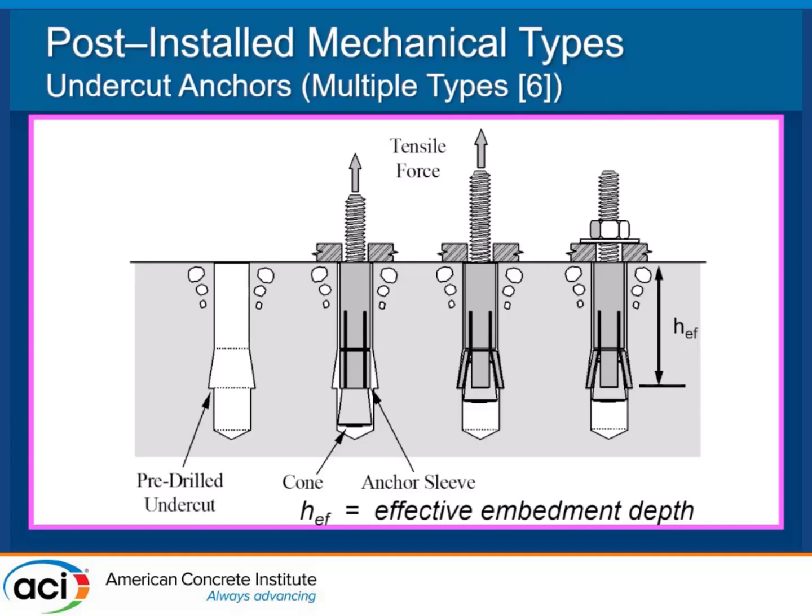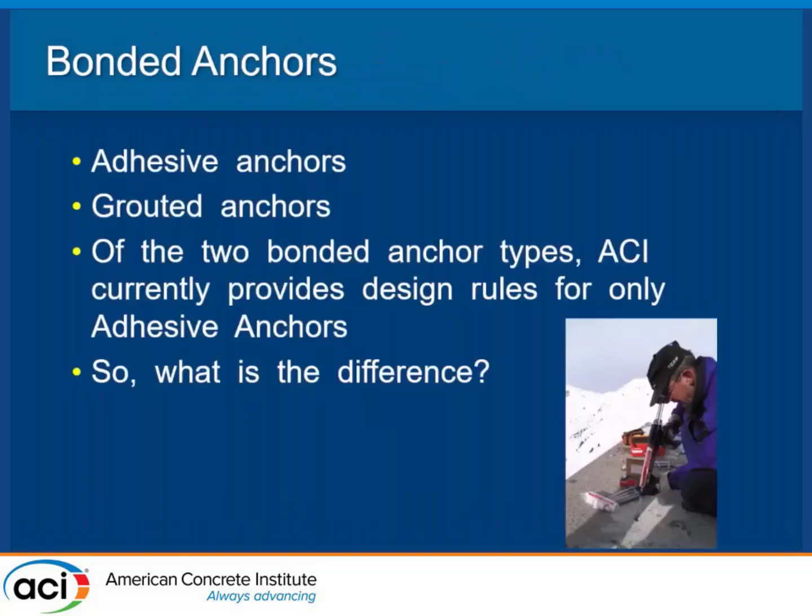You're widening out the hole, and then when you put the anchor in, you're actually kind of getting that headed anchor that you might have cast in. It acts very similar and does extremely well. But it's more expensive to use, both in construction and historically they've been more expensive, although I haven't looked at cost in a while.